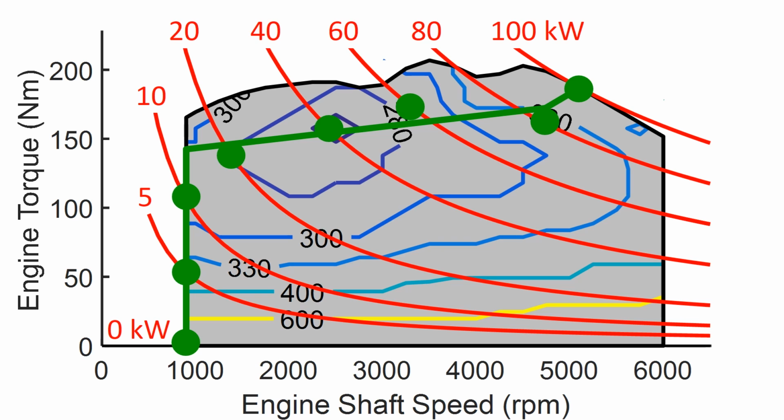Since a normal gearbox only has a limited number of gears to select from, the optimal operating point will most of the time deviate from this ideal operating curve. However, the operating points will be selected so that they are close to this optimal line whenever that is possible. A simplified but still very fuel-efficient gear selection strategy is to always select the gear which gives the highest engine torque. Due to the limited number of gear ratios to select from, this simplified method will most of the time lead to the same gear being selected as for the detailed method presented earlier in this lecture.